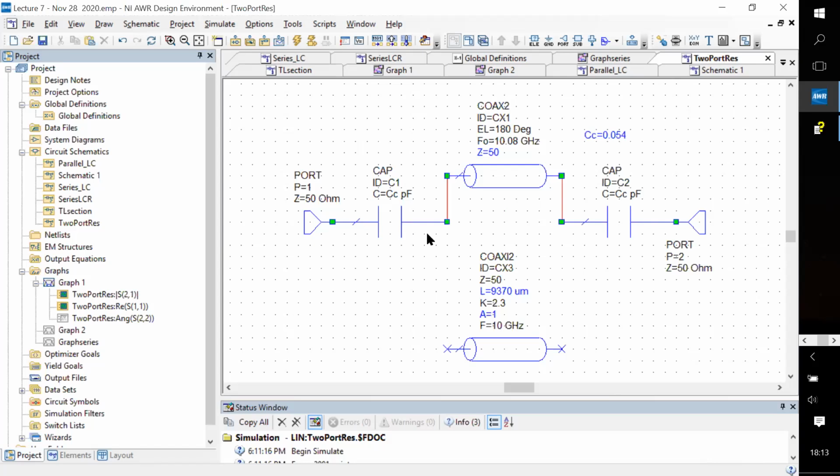However, the correct way to think about it is that if I had some energy in the oscillator to start with, and I just let it go, where will that energy go? And there is absolutely no way to distinguish this side or that side in that context. So the power will just decay from both sides, and both sides will contribute equal amount of loss because they are exactly the same, and they will add to give you the total loss and the Q factor. So maybe this will be an exercise where you can compare how a single port resonator with a coupling capacitor of CC and a 2-port resonator with 2 coupling capacitors on either side, what the relative Q factors are. Okay. All right, good.